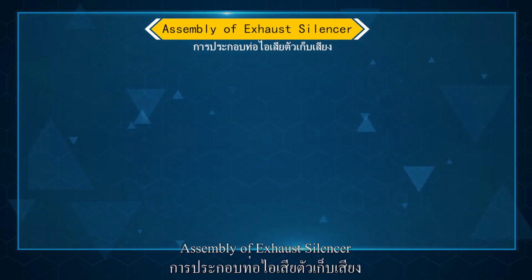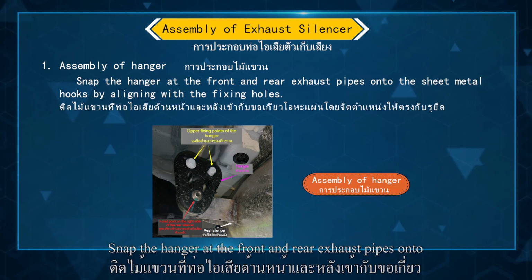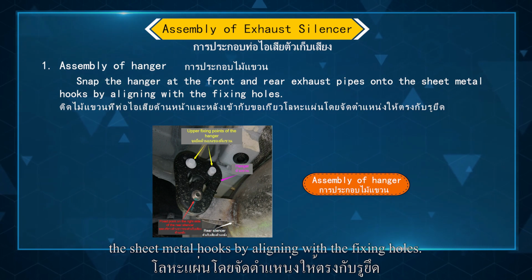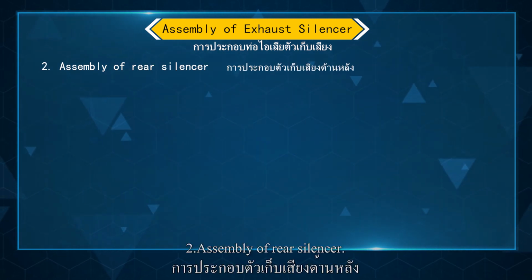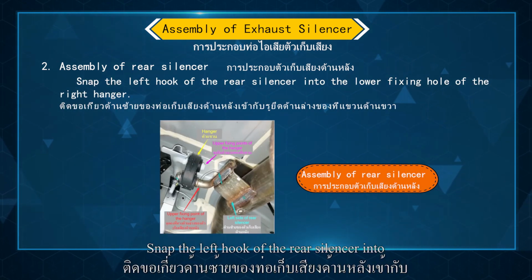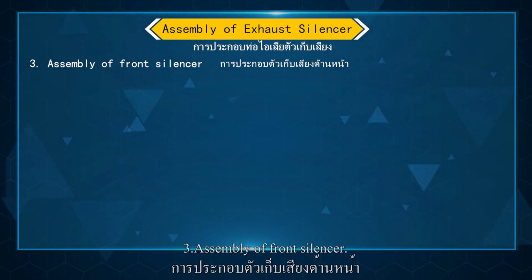Assembly of exhaust silencer. 1. Assembly of hanger. Snap the hanger at the front and rear exhaust pipes onto the sheet metal hooks by aligning with the fixing holes. 2. Assembly of rear silencer. Snap the left hook of the rear silencer into the lower fixing hole of the right hanger. 3.